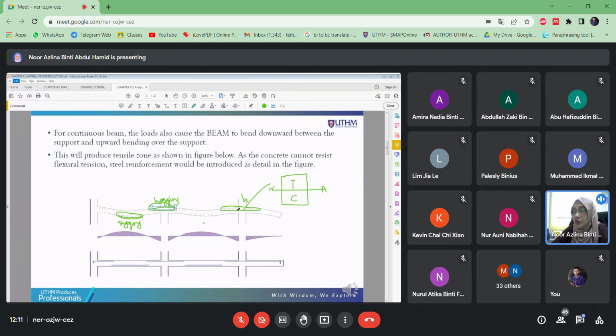So that's why we will put the reinforcement at the tension area within the columns here, because the top one becomes the tension, while in these sections here, the bottom one is in tension, the top one is in compression. So that's why cracks occurred first at the bottom.